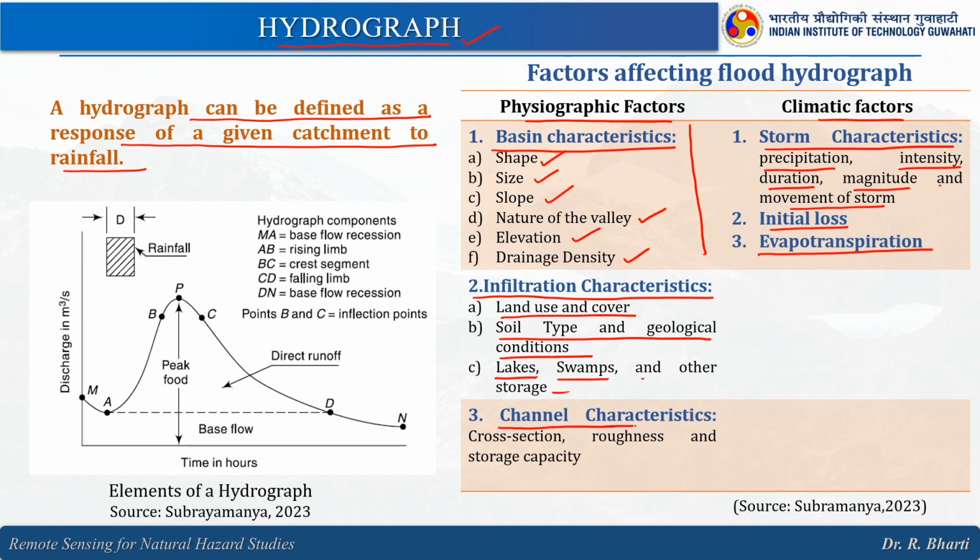Then comes the channel characteristic: the cross section, roughness and storage capacity, whether it is a wide channel or a narrow channel. And what is the duration and the intensity of the rainfall. So, all these we need to consider while analyzing this hydrograph.